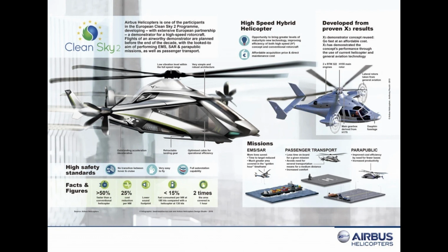Air conditioners or heat exchangers can be fitted to the helicopter as well. They operate by drawing bleed air from the compressor, passing it through the heat exchanger and then releasing it into the cabin. As the compressed air is released, the expansion absorbs heat and cools the cabin.